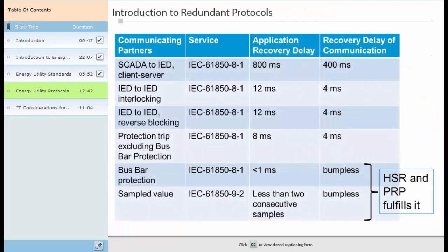Substation automation systems need to ensure continued services and have to incorporate fault-tolerant solutions. That is why the Network Communication Redundancy Protocol represents one of the paramount parts of a substation automation system. To survive network failures, various standard redundancy protocols can be used depending on topology and convergence time requirements. For example, Rapid Spanning Tree Protocol, Media Redundancy Protocol, Parallel Redundancy Protocol, and others.